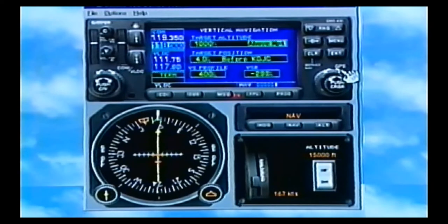Basically, I'm flying Mooney airplanes here at Garmin, so I like to be at pattern altitude. The factory defaults are 4 miles out. I like to be at pattern altitude about 3 miles out. So I like to be 1,000 feet, pattern altitude, above waypoint. That would be whatever waypoint my destination waypoint is. And with the little knob, I can change my position here to 3 miles. Well, that's pretty consistent. Almost every airport I'm going to, I want to be at pattern altitude 3 miles out.